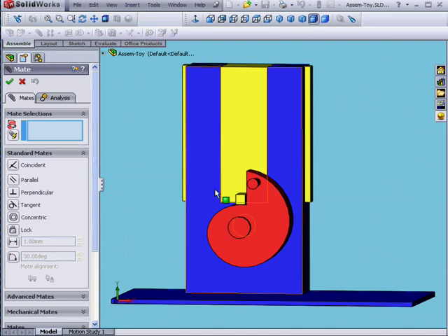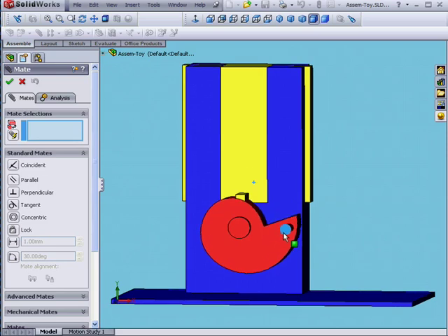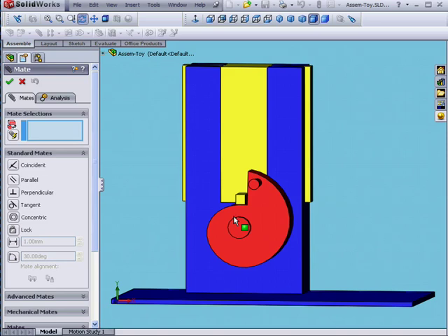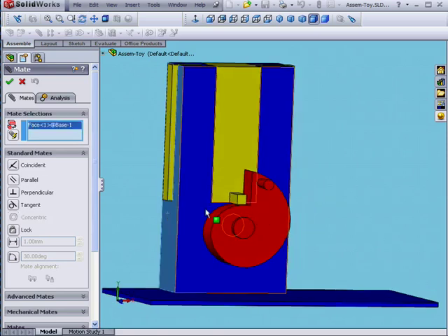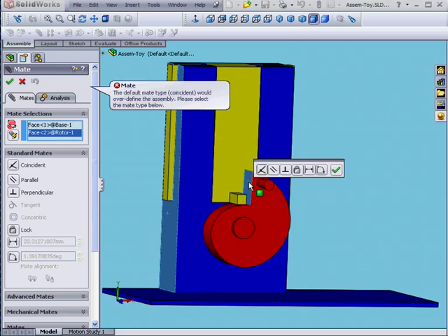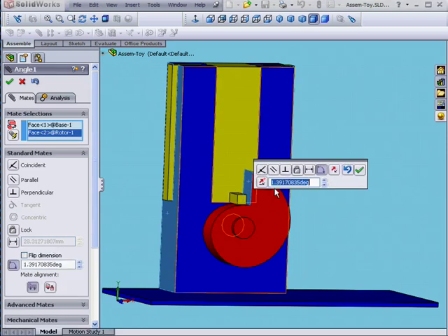I'm going to create this mate in a way so that the initial rotor position is 0 degrees. And then it'll move to 90, 180, 270, and 360. It's easy to do this way, and it's less confusing for SolidWorks too. I'm going to select this face, and then this face. Now we select Angular Mates, enter the value at 0 degrees,